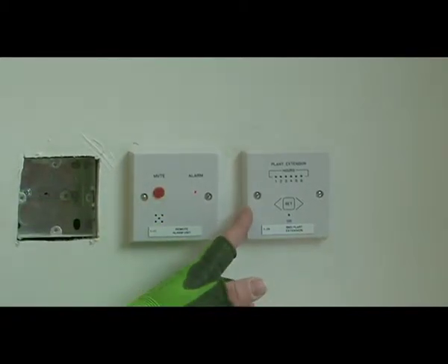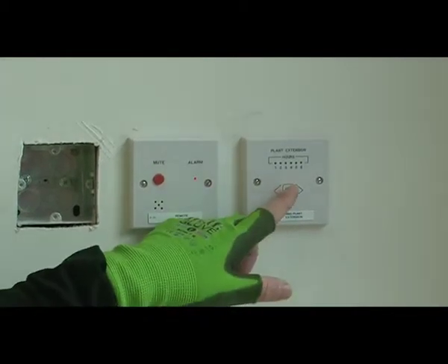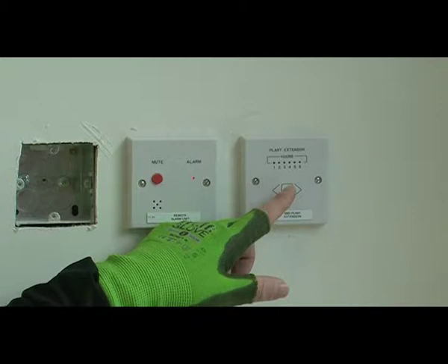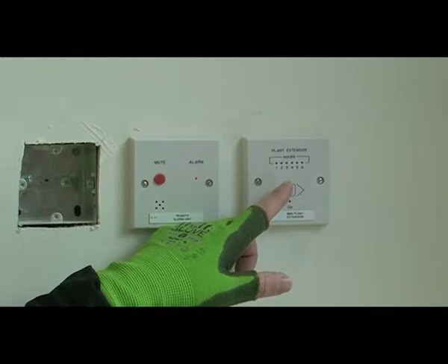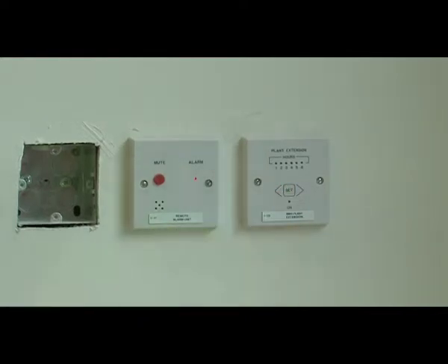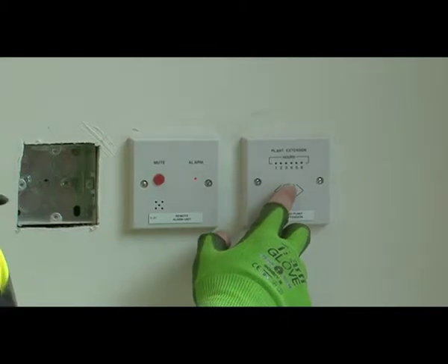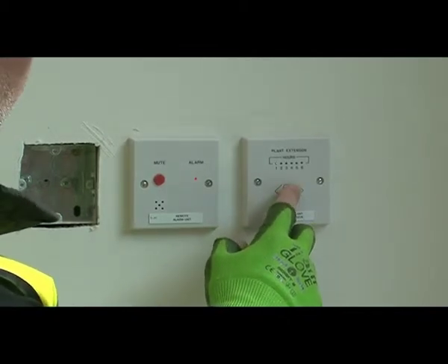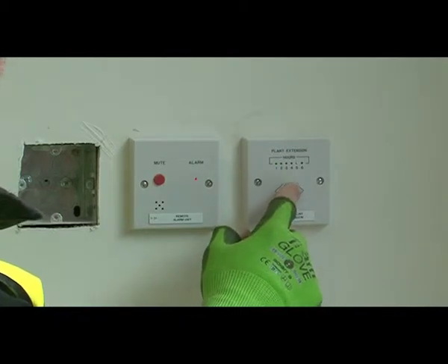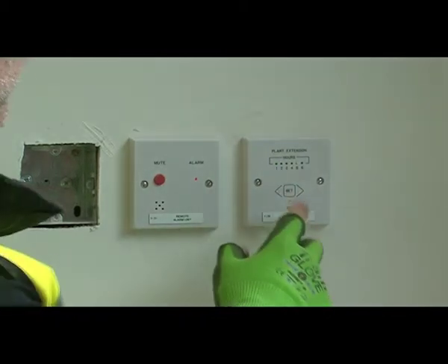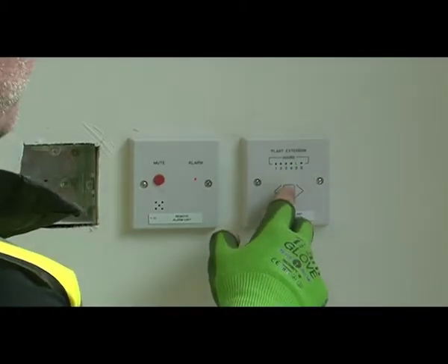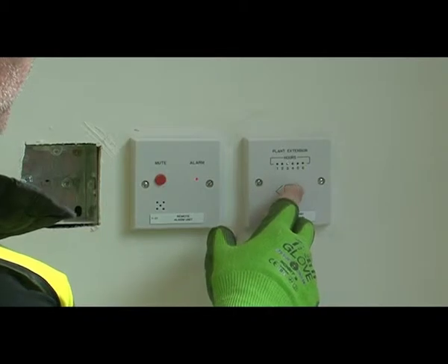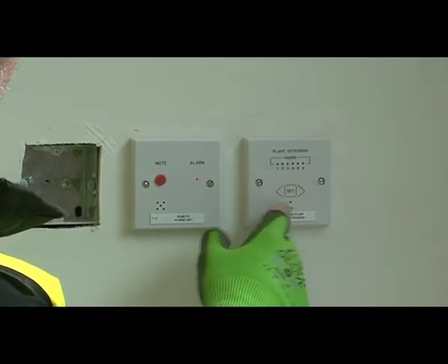Adjacent to this we have the BMS plant extension. If you don't want to change the times on the BMS system, but you would like the building heating to be on and the ventilation in the kitchen to run for another 2 hours, say, after your normal closing time of say 3 PM, you can just set the extra time by this push button. Press it till it lights the number of required extra hours you need. This gives you up to 6 hours, and then that's set on, and that will give you 5 hours after your normal building end time. To reset this, you can just press the set button till it reverses back to off, and that's shown by the on-off lamp there.